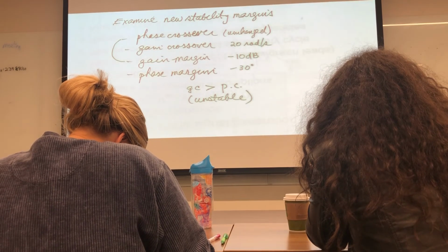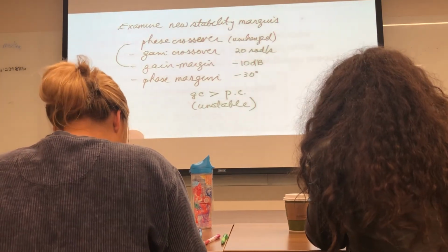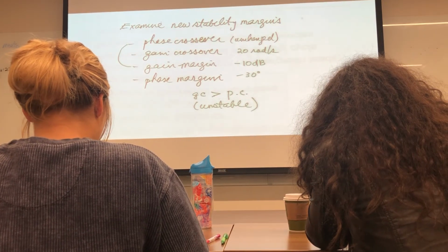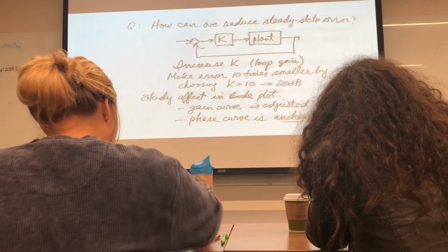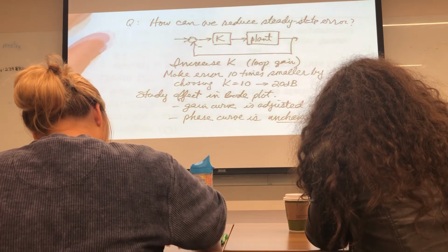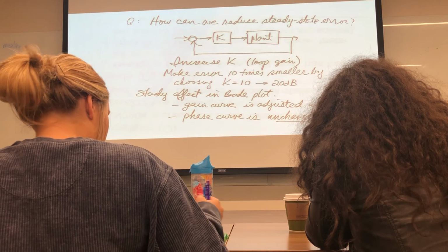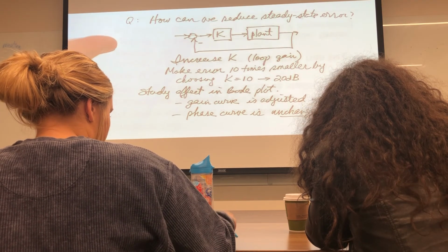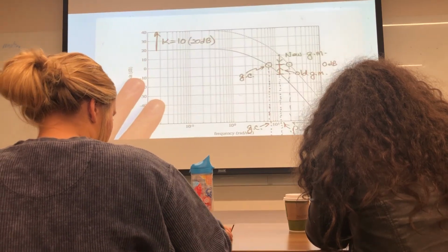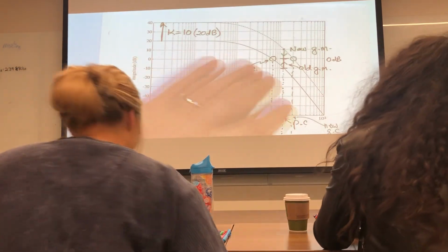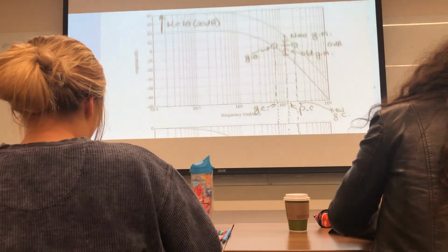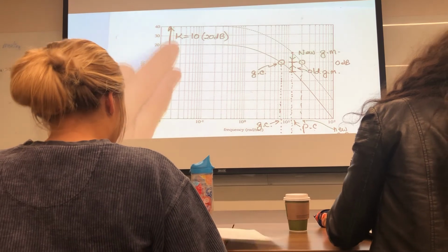All right, so what we've attempted today is to try to reduce the steady state error of a control system by increasing the gain, and by studying the stability margins, we discovered that this is not going to work. So in the coming days we're going to ask, is there a way for us to reshape the plots? That's what frequency response design is.